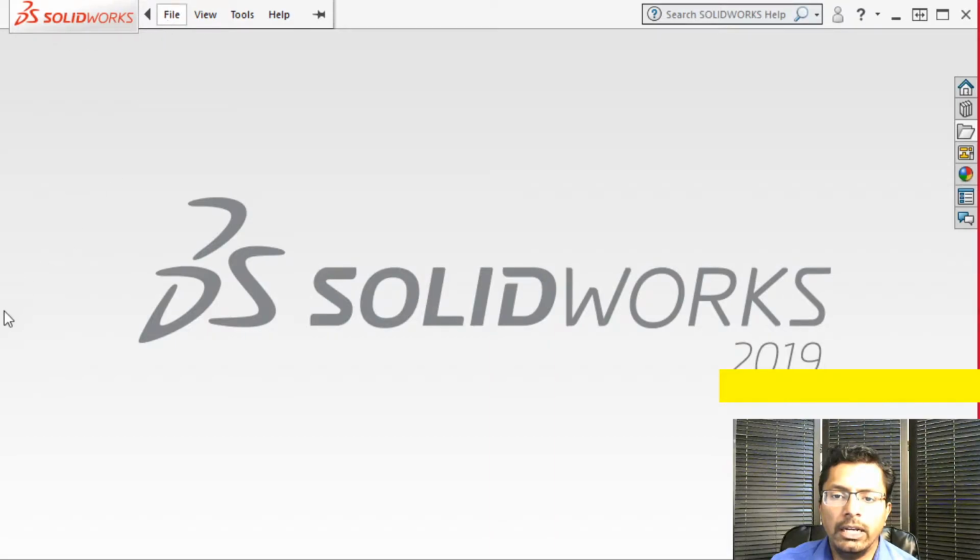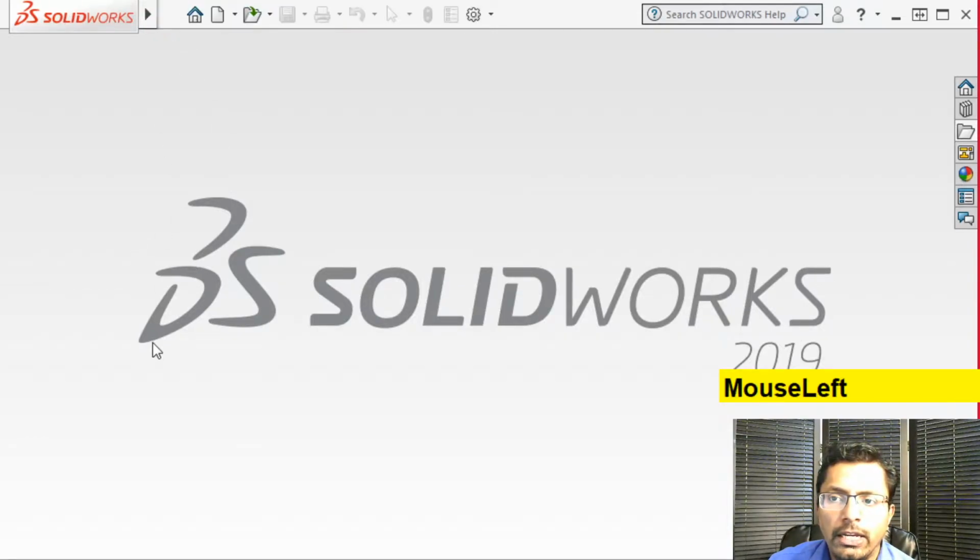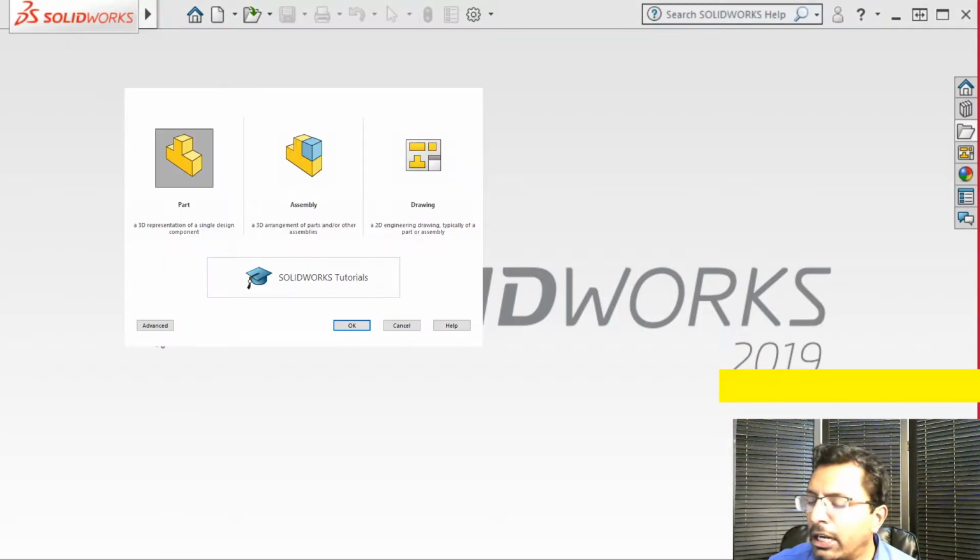Then I can go to file, and if I go file new or control N, it's going to open up a new screen that I can use. Here is where I would select all of the things that I need to. I'm going to create a new part, and then we're going to click OK.